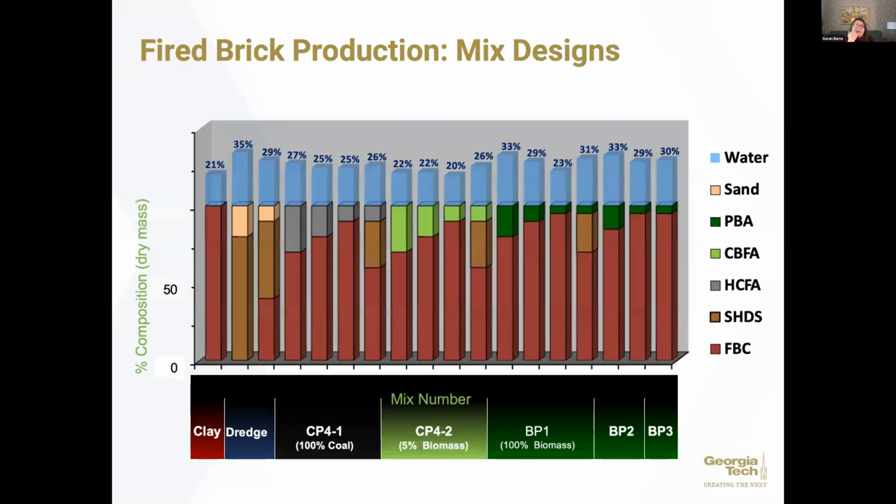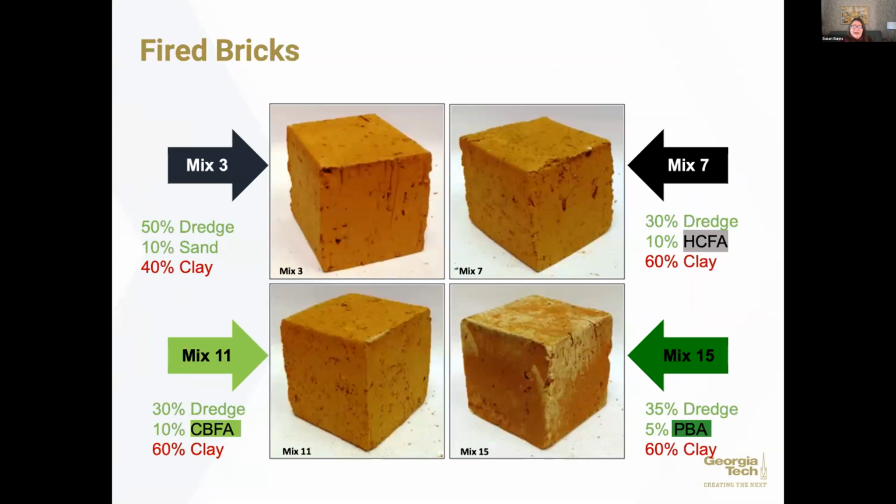weathering. So you can see here we tested a range of mix designs, and this is like a recipe where we've got some component of sand. We mixed in our off-spec ashes, we mixed in the dredge sediment, and then we mixed in clay, so normal brick clay. And you can see we tested a range of volumes here, along with some different water contents as well. And it turns out we made really great bricks. Actually, they were really quite beautiful.